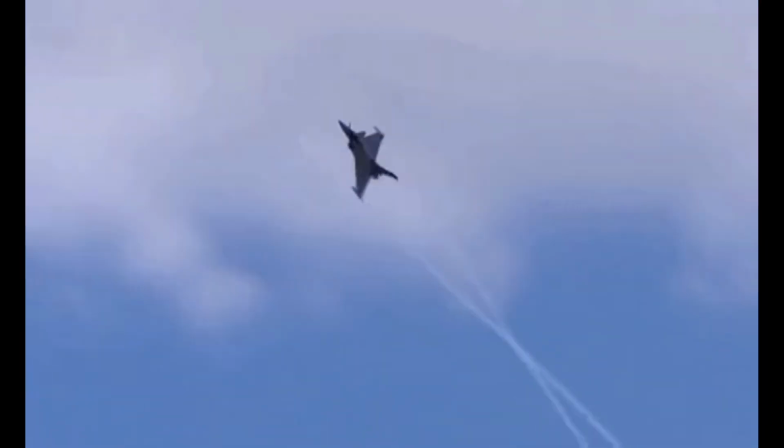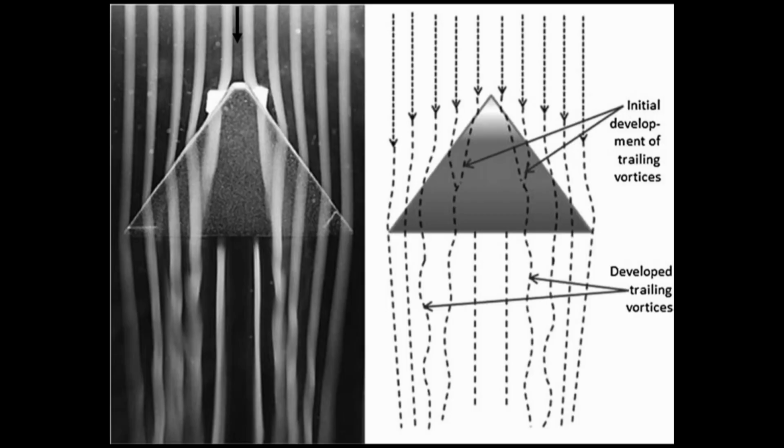An understanding of the concepts and equations helps determine an airfoil's dynamic efficiency, stability, scale, shape, and more. In supersonic flights, to reduce shock waves at high Mach numbers, delta wings are used to split the flow into two perpendicular components, slowing down the flow over the wing.